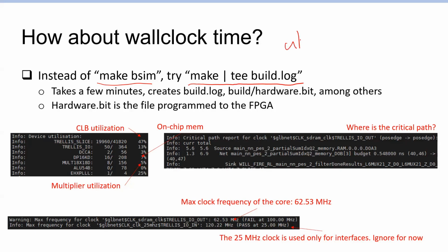Inside the ULX 3S directory, I think there's a tools directory where you have to go inside and do make. There are some support binaries you have to build, but inside the Git repository there should be a piece of text that describes how to do this, in the readme.md.